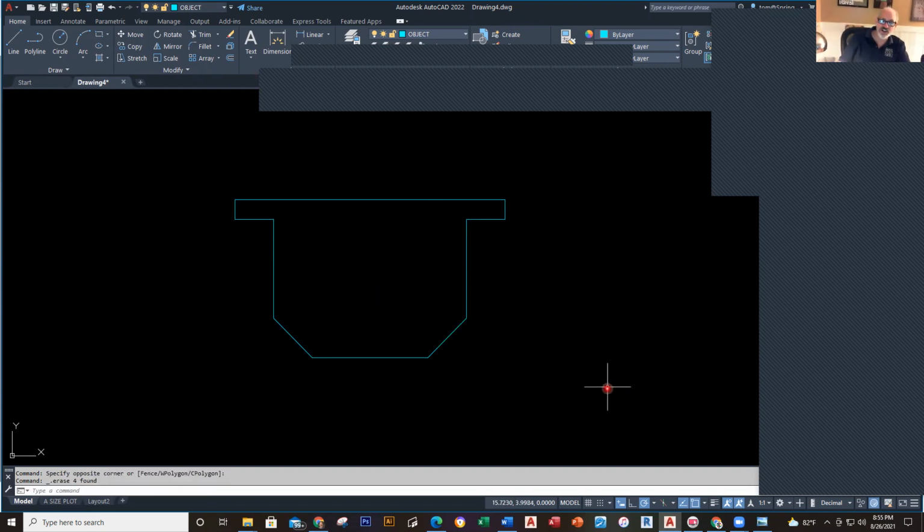Okay, now using our object snap tracking is another really cool way to do this. I start the line command, I touch it without clicking here. Then I pull it over. And I haven't told it, I haven't clicked. So now it's asking me, well, how far do you want to come off this point? So I type in 1.5 here, and then it starts it. And so this way, I don't even have to go back and erase it when I'm done. So I'm just going to go through here. And I go over. That's another way. So those are the two ways you can do it.